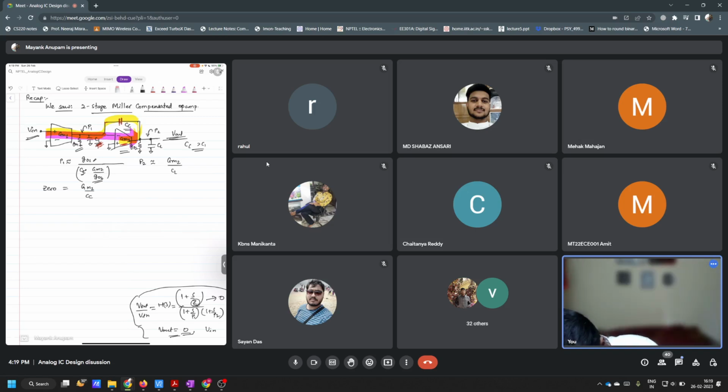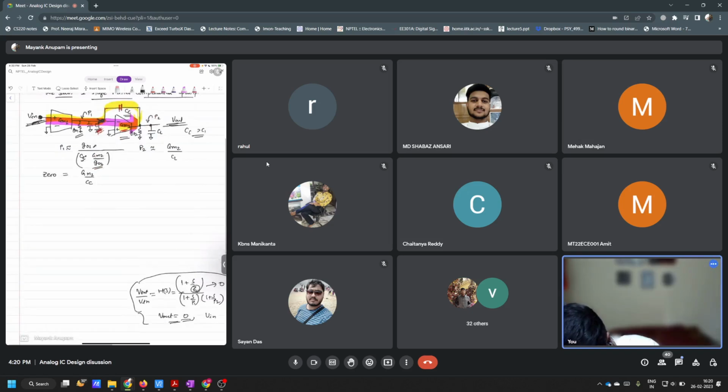So first of all, from input, which is here, we have same path up till here, right? Up till this, everything is same for both the paths, right? But right from here, we have these two branches which are bifurcating from here, right? And then they are again combining at the output. Okay. So any signal, any current that will pass through this CC and which will be going through this GM2, they will have different phase shifts.